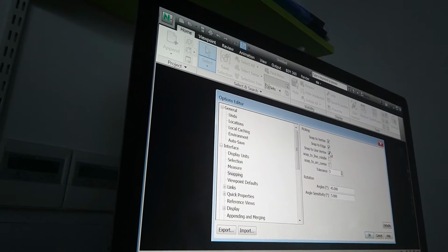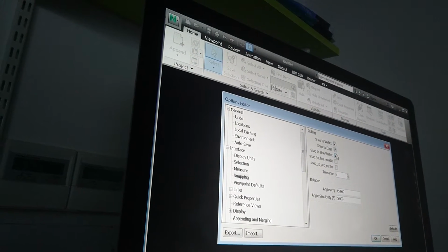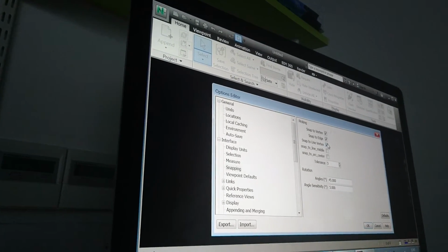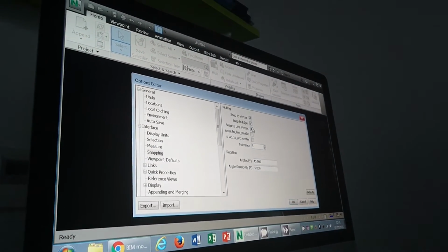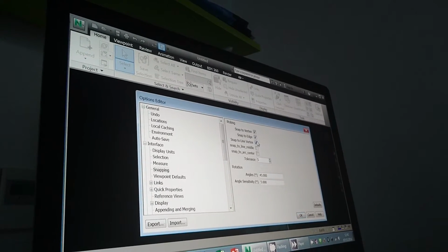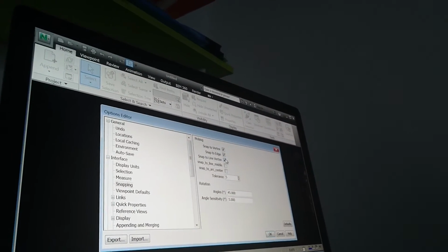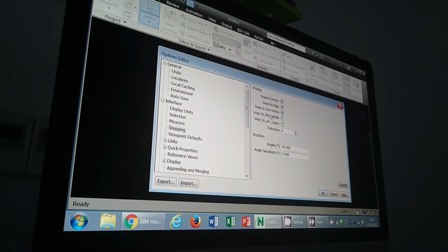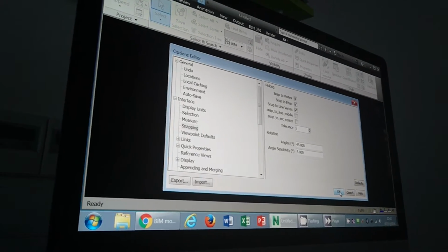basically you'll be able to snap some main points, but you want to snap the edge of the pipe, the edge of some item. So by default you can't do it. So simply you have to firstly go to the options and click on it. So from now you'll be able to snap to any edge, which is in my opinion really important. I'll show you why.